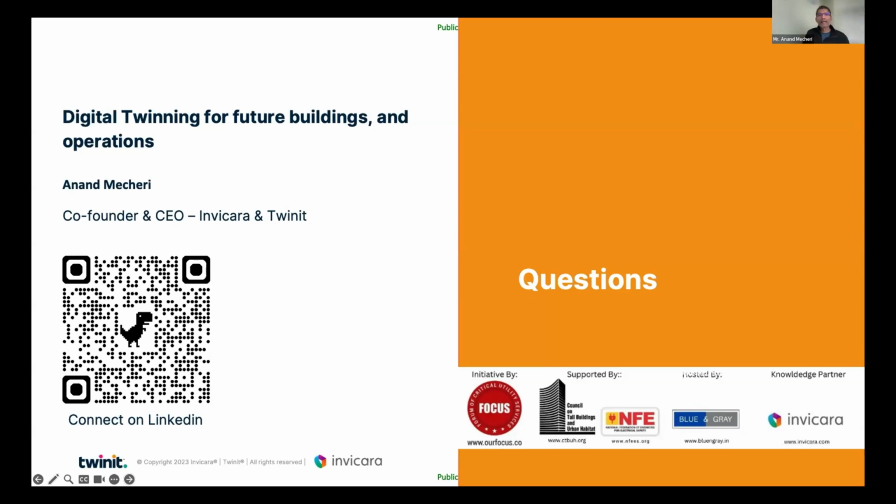Will data from sensors and actuators in the real world trigger alarms in the digital twins as a precursor to physical failures? Yes, absolutely. By defining the expected behaviors of your entities in your digital twin, you can assess that against the real-time data. It can be rules-based, it can be machine learning-based, but definitely digital twins can detect and notify these sorts of anomalies and even give recommendations for improvement as part of your solution.